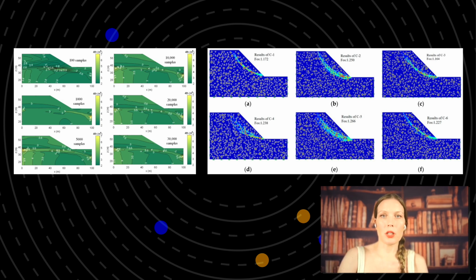Another important dimension is probabilistic analysis. Since soil properties are never known with absolute precision, engineers must ask, okay, so what if the soil is weaker or the load is higher than assumed? Probabilistic methods such as Monte Carlo simulations allow for variability in input parameters and estimate the probability of failure. If the likelihood of slope failure is significant, this indicates the need for additional reinforcement. While such advanced approaches are less common in everyday practice, interest in them is growing, especially for high-risk or sensitive projects.